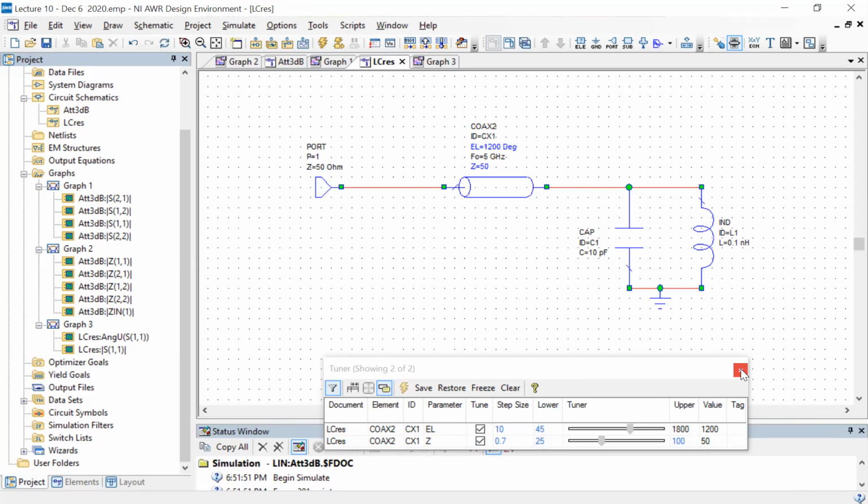There are other ones which use semiconductor pin diode switches, where essentially by changing the diode's biasing condition, you can make it into a short or an open. So those are electronic pin diode switches. They have less ideal properties in terms of reflection and also insertion loss. Like it might not be a perfect connection. There'll be some attenuation in it, but they can be switched very, very fast. Like in nanoseconds, in tens of nanoseconds, you can go back and forth between an on and the off state. So that also has some advantages.